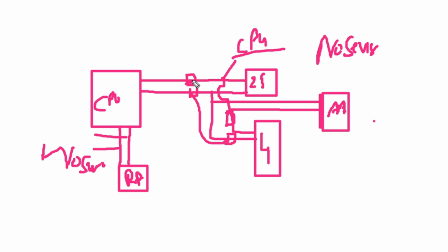You can jumper it from data to data, clock to clock. But if the line is damaged internally, directly to the CPU, you can't make a jumper from these lines. You would have to open the CPU. Also, if you check these lines, this is a pin IC, so you can check directly on the pin by attaching your multimeter needle.